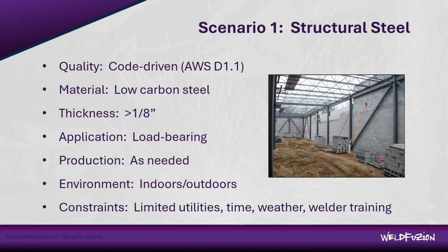Well, let me tell you, if you considered stick welding because of its ease of use, extreme portability, and you're able to run it off just about any generator, right, if you need to, you're going to be making short welds, so who cares if you've got to stop and change your electrode? It's not a factor, but it does really well in terms of weld quality in the environment you're working with.